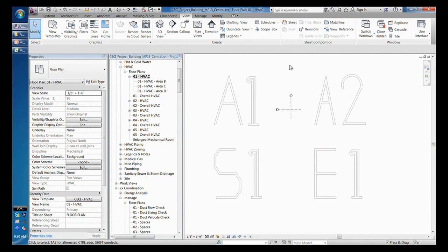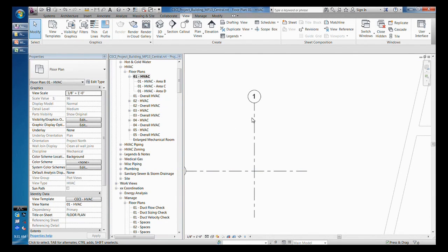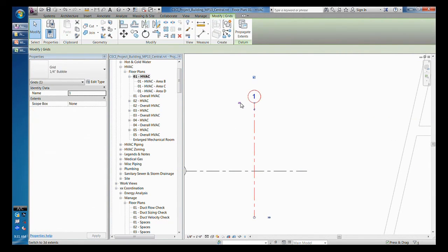But that is the same for them too. Now, if they actually do the grids with the 2D instead of the 3D, that will be for that view only. So if they do it in the linked view, it comes through for me fine. So for example, this is the 3D, and they switch it to 2D, and now they pull this to be that short. That's the 3D bubble up there. In this view, they fixed it. As I link it to that view, this is how I'm going to get it as well. That resolves this as well.